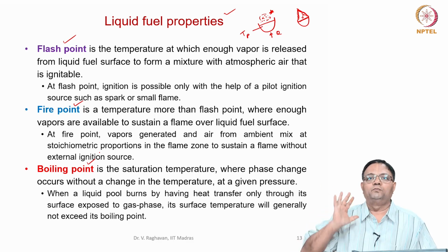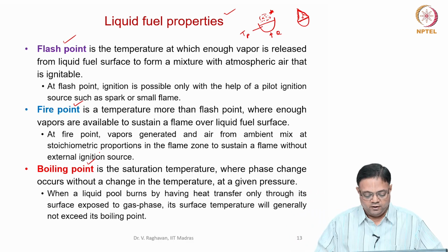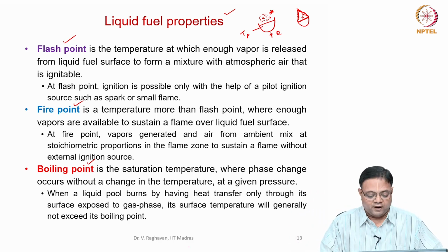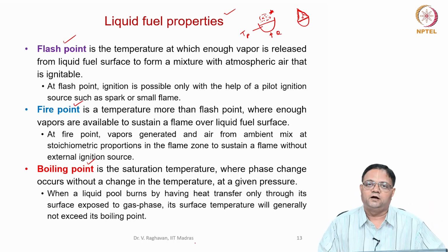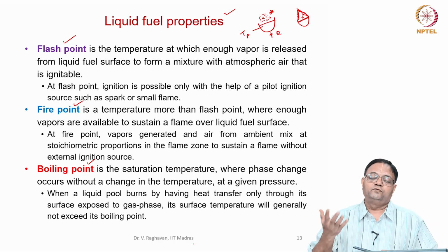Entire volume is at boiling point. That means you will see that the temperature further will not change until the liquid is converted into vapor. So, boiling point is called saturation temperature, where phase change occurs without causing any change in the temperature until the entire liquid converts into vapor.